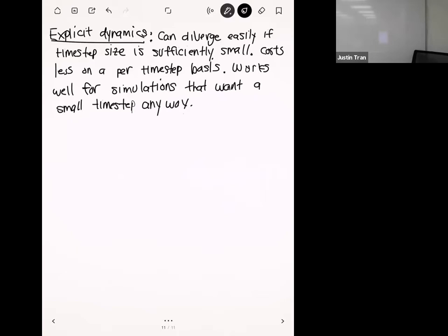Why does yours look like that? We're not going to update these until the summer, unfortunately. Your force is extremely high, and your pressure is super high to have 5 megapascals. I'm assuming there's a point load for boundary conditions on the tires first.